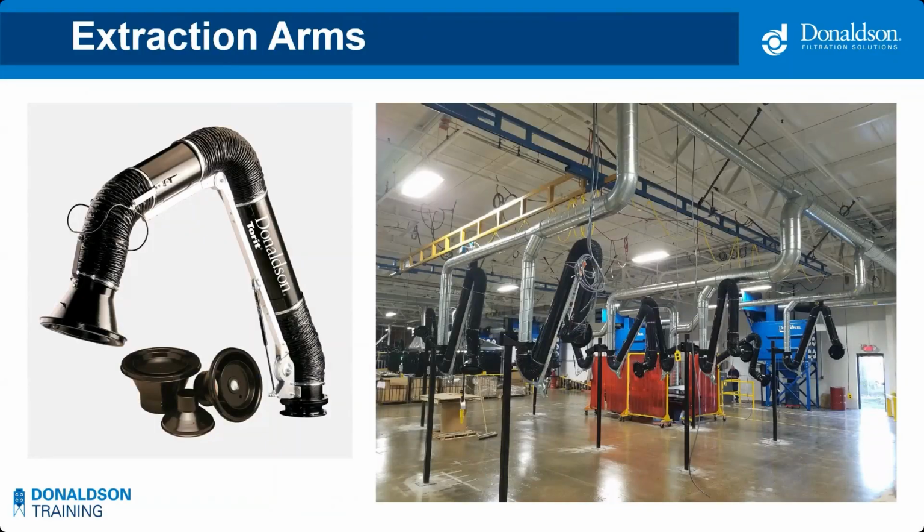Extraction arms with a bell mouth hood on the end is another good solution for small weld applications, like those found in schools. They come in various lengths and diameters. The picture on the right was taken prior to the curtains being installed, but each extraction arm is where a different weld station would be located.